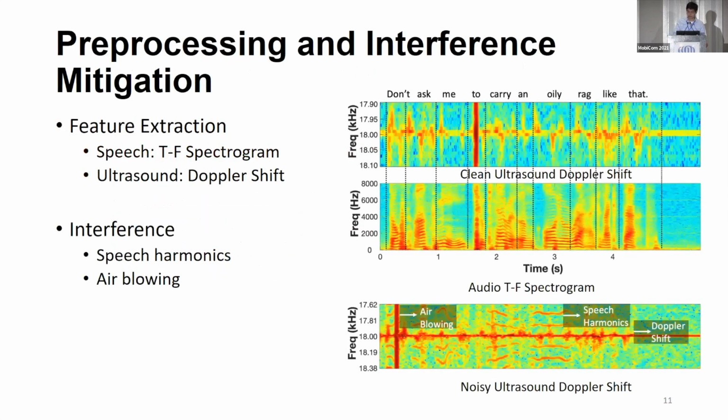After receiving the sound signals, we try to extract the single-stream audio into two different modalities. We extract the time-frequency domain speech spectrogram for audio and the time-frequency domain ultrasound Doppler spectrogram for inaudible sound separately. Although these two modalities have different frequency bands, we find that mutual interference exists between speech and ultrasound, which causes ambiguity of the Doppler features.